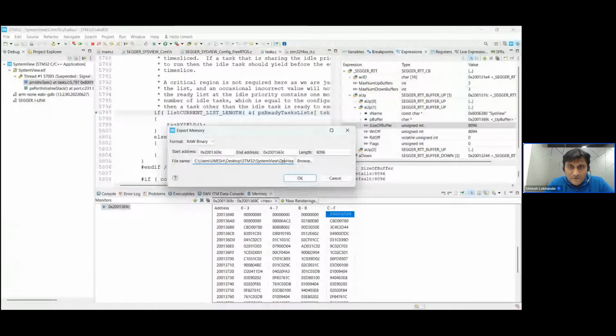And now, because I captured the fresh new event, and remember what I said, when we export this debug information manually, I will have to store it with the file name DevHeads, let's say 007, James Bond, and .svdat format, right? So remember I said this information will be exported into the svdat file format. And this file will be generated into the SystemView folder, which is on my desktop in the STM32 project.